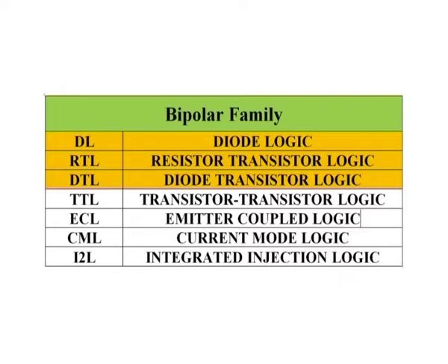TTL and CMOS devices are grouped into functional categories that get placed into either 7400 series or the 4000 CMOS series. Now, another series you will run into is the 5400 series. This series is essentially equivalent to the 7400 series with same pinouts, same basic logic function, but it is more expensive chip because it is designed for military applications that require increased supply voltage tolerances and temperature tolerances.